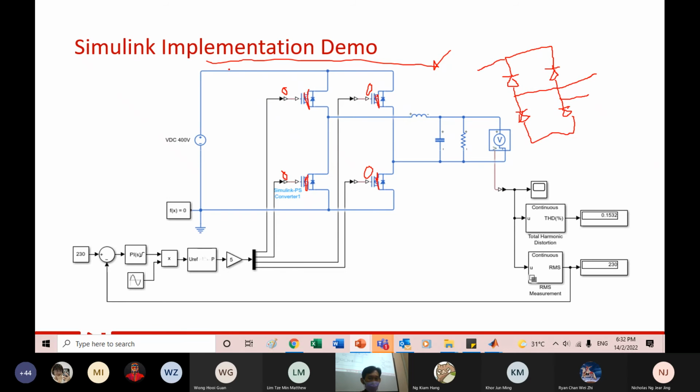And then of course, you need to have a capacitor to do the filter, right? That's why the capacitor has to be there. So when you turn off all these, send all 0 to this, your inverter becomes a rectifier and if power goes in, it will start to charge your battery. As simple as that. And they sell you how many thousand USD?